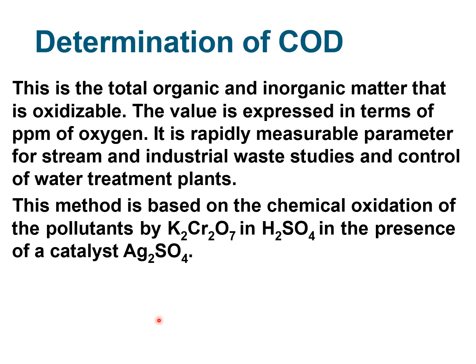Next one, the determination of COD. It is nothing but chemical oxygen demand. It is defined as the amount of oxygen required in order to oxidize the inorganic impurities present in water. Here, the experimental procedure is based on the chemical oxidation of pollutants by using potassium dichromate in sulfuric acid in presence of a catalyst Ag2SO4.